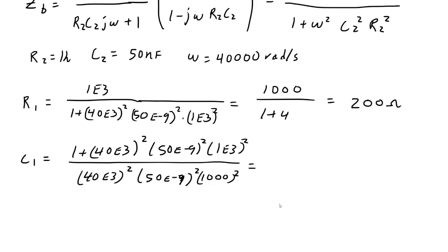That's going to end up being 5 divided by 80 million. So that's going to be 0.0625 microfarad or 62.5 nanofarad.